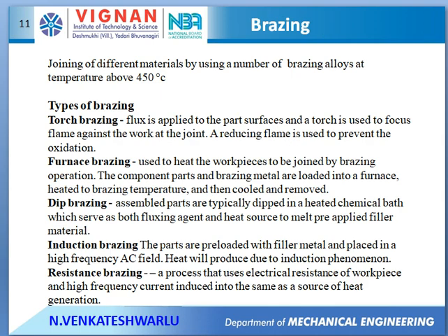Brazing is similar to soldering, except its filler melting point temperature must be above 450 degrees centigrade, and at the same time it is below the melting point temperature of the base material. And in case of brazing also, the filler material is supplied by means of capillary action. The usual filler material in brazing is copper alloys, and the flux material is borax and boric acid.